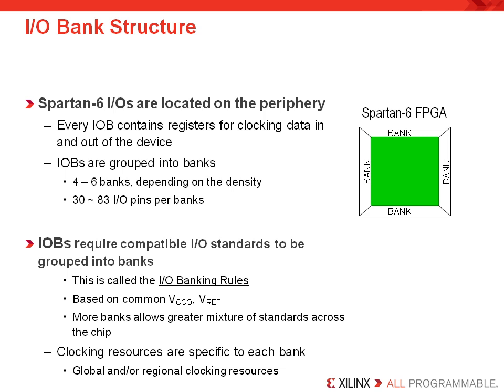In fact, using the registers to clock data in and out of the device is the fastest way to move data in or out. Besides the registers, the IOBs contain interface logic that is designed to translate the internal voltage domain of the FPGA to whatever I/O standard you're using outside the FPGA. This saves you from having to add all the necessary interface logic outside of the FPGA. This requires that each bank share a common power supply for inputs, called a VREF, as well as the power supply for the outputs, or VCCO.